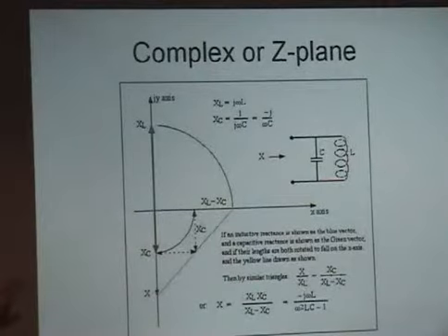Tank circuit. And this is very interesting because I can take an oscillator against this, and if the oscillator is not quite in sync with the resonant frequency of the tank circuit, it will straighten out the frequency. This will stabilize the frequency of an oscillator which is tending to drift with temperature. It's interesting.